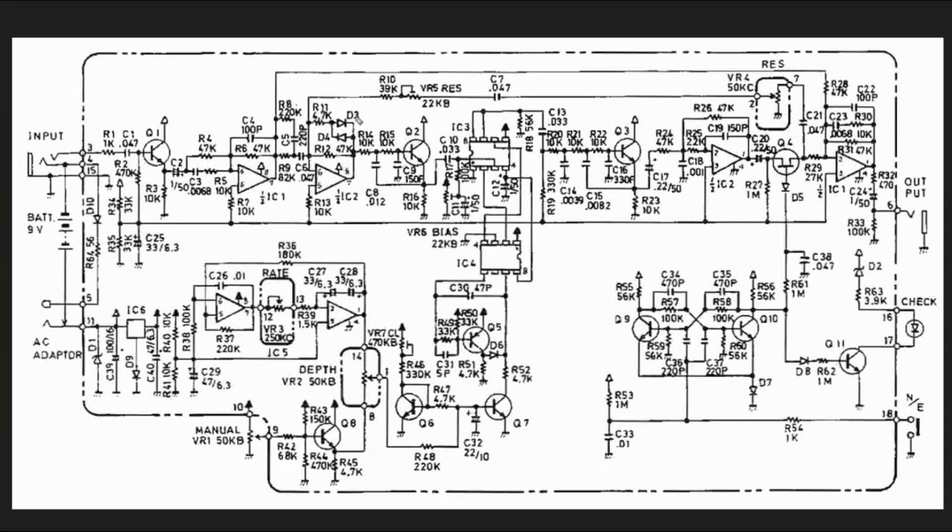On the output of that summing amplifier and limiting stage, we have a two-pole Sallen-Key low-pass filter here. In the Boss CE2, this is actually a third-order filter, which means it has a steeper roll-off of the high-frequency noise, but this is only a second order because it's going to also be rolling off the summed-in feedback that comes in. The extra order for the input from the guitar, though, happens with these components.